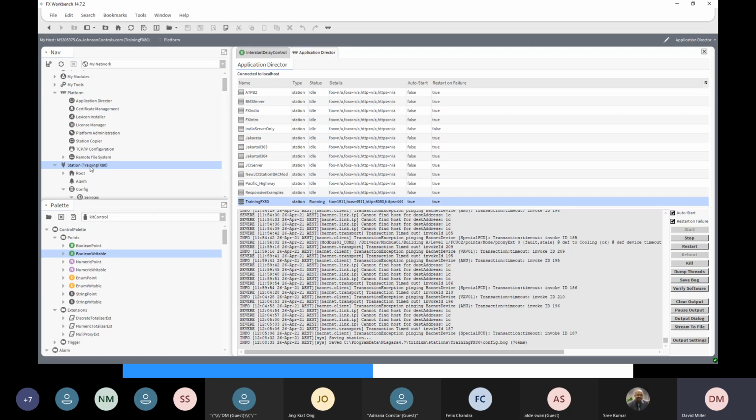So if you had an FX server that's supervising a big, large site of FX80s, and you needed to do some data gathering across all of those FX80s, then you could do that work, like a cooling call or a high select, or maybe sharing outside air temperatures. You could do that work in the FX server if that was appropriate. So logic in a Facility Explorer system can exist anywhere on any station.